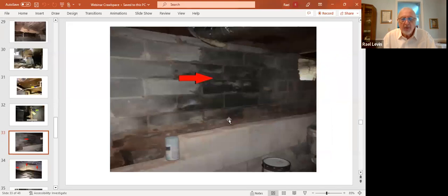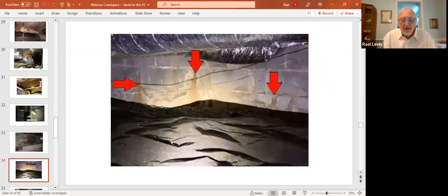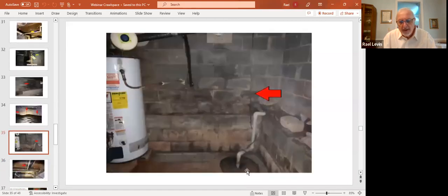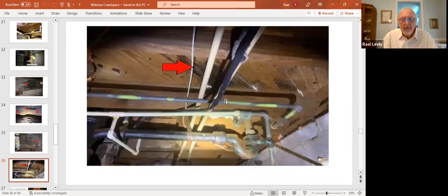And then we can see again the moisture on the outside wall of the foundation, where we see that moisture here. Terminology, efflorescence. We see that white powder and stuff on the inside of the foundation. So even here with that moisture barrier, we do see water intrusion, which would need to be addressed there. We do have that sump pump located down here again in a crawl space area. And again, at the corner. So it could be just the small issue of going ahead and putting in an extension to the downspout bottom elbow.